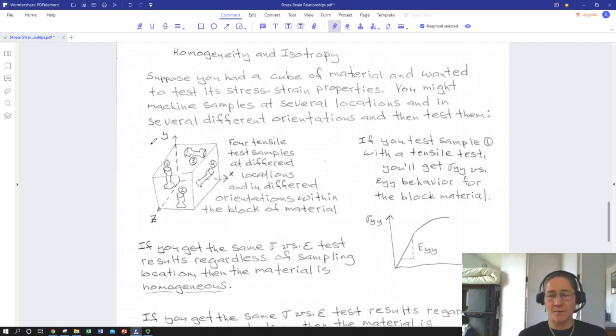A composite, absolutely not. The fibrous reinforcement is going to have a strength and, more importantly, a modulus, maybe orders of magnitude more than the matrix. Okay. Generally in our course we're going to assume that everything is homogeneous unless otherwise stated. So we're going to be looking at things on what's known as a continuum basis. So that means we basically take all the crazy mechanisms that contribute to a material's elastic properties and yield properties and treat all of those as a single number.